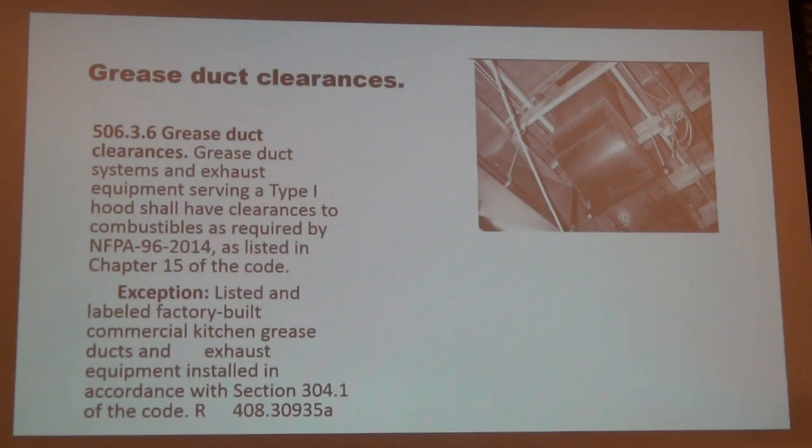Okay, it's 18, and then they have something in NFPA 96, not clearance reduction, they call it limited combustible. Drywall. And yes, it's 3 inches.